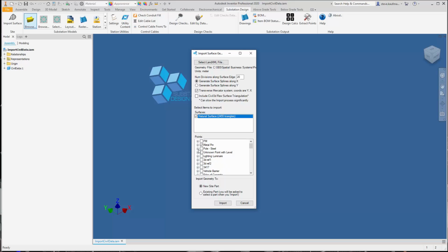We have several metal pins. If I expand this, you can see these metal pins. And I'm going to scroll down. I'm also going to bring in points. These are all going to be work points for the roadway. Edge of road. So I'm going to bring in the edge of road just for information. It's the pins that are going to be my pins for georeferencing.